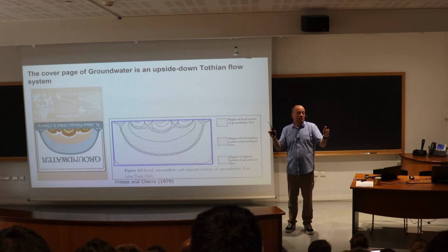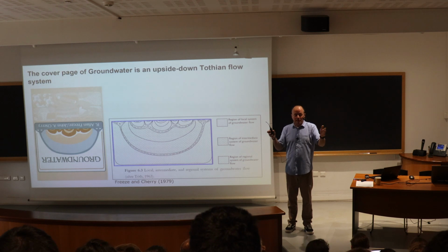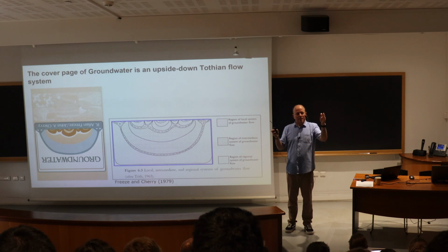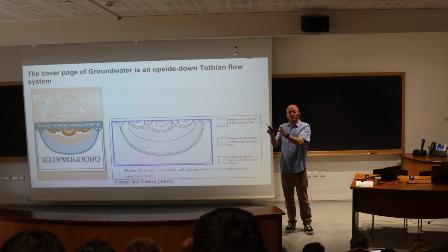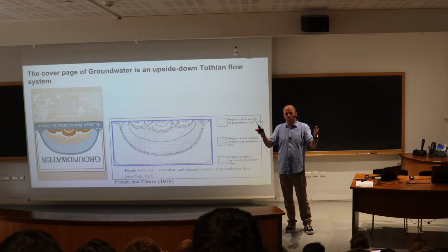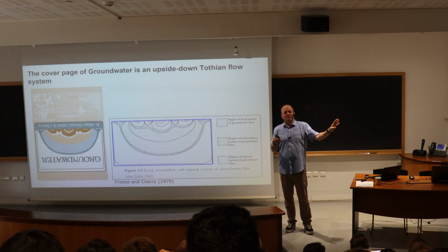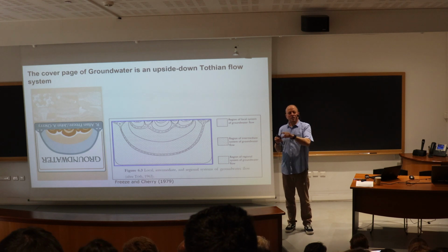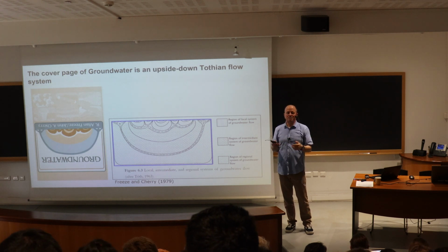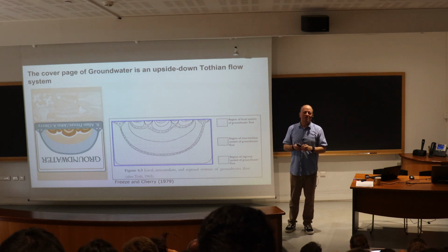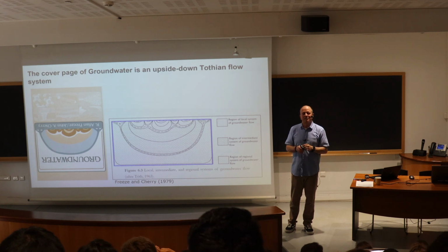And he actually tried different things. He tried incoming regional flow, fixed hydraulic head, uniform hydraulic head, impermeable, and then he compared his results. He was focusing on the lake. He found out that the further away boundary did not make much of a difference on what he was observing, but it was our best educated guess because we didn't really have data.